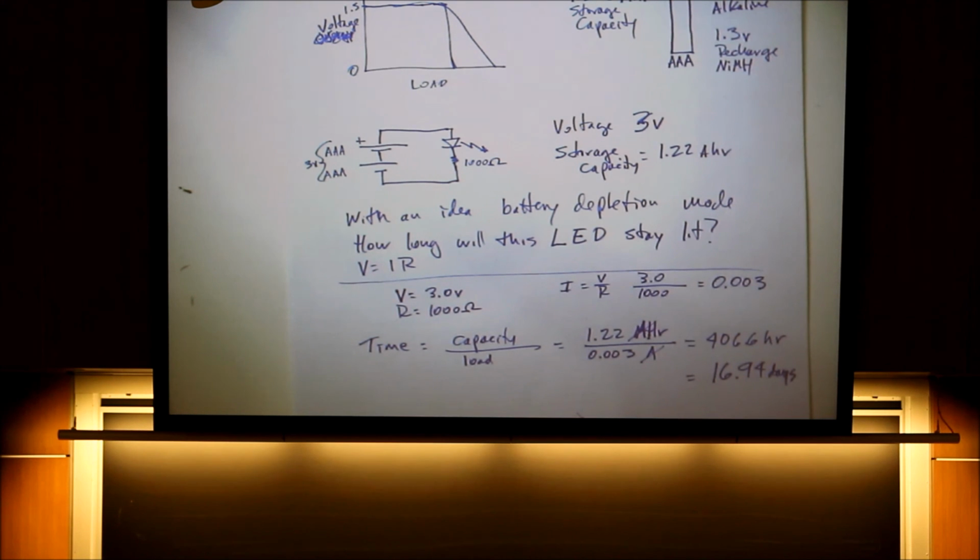And you will, as we call, release the magic smoke. Because in electronic circuits, it's the smoke that they put inside that makes it work. And when you release the magic smoke, then it doesn't work anymore. So when you actually build the circuit, you should put the resistor before the LED, otherwise that will happen. Well, it doesn't matter which one, because don't forget the resistor will limit the current no matter where you put it in the circuit.